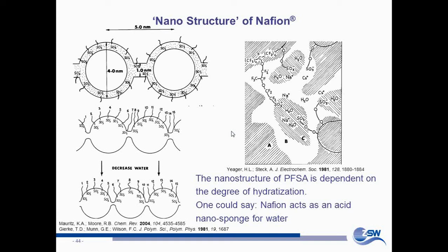And you find a very, very strange behavior of these materials. If you take a piece of these perfluorinated sulfonic acids, dry it in an oven, take it out under ordinary conditions, throw it on a balance in an ordinary climate, maybe not in the desert, then you will see the weight increasing and increasing, since the material is highly hygroscopic, it absorbs water from the atmosphere.